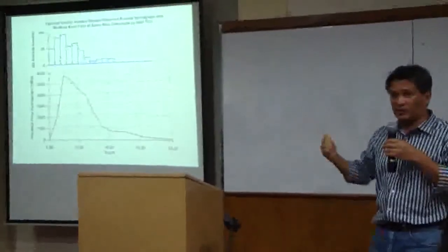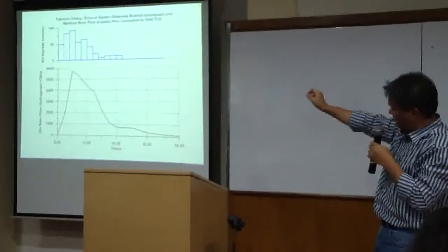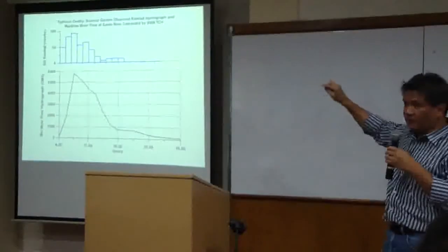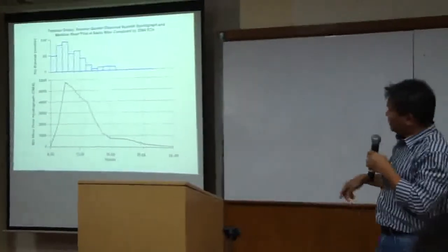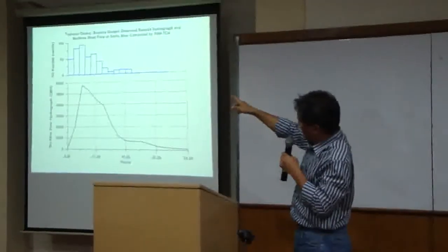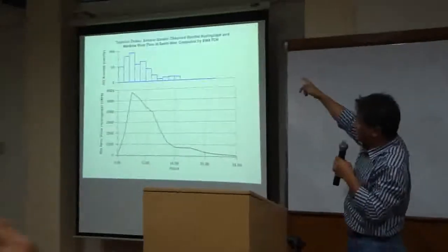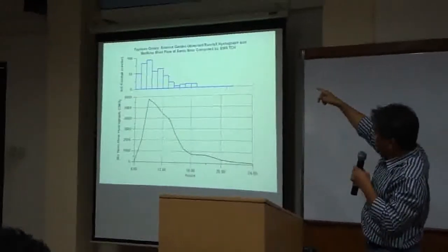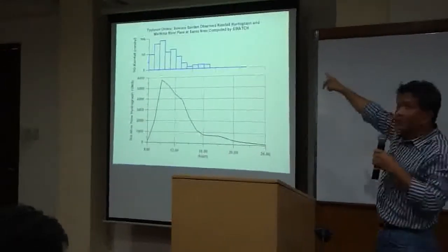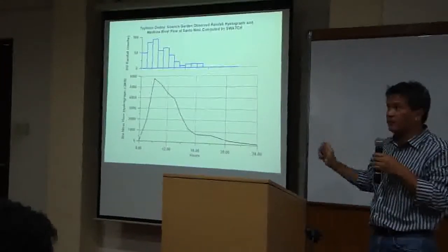Then we run the watershed model, which is a 15-minute watershed model computation. So we should assume that it's uniform over the 1 hour. So essentially, you started with something like 6 millimeters. I didn't put it there anymore, but it went to 49. It went to, I think, 69, and then 92 was the peak. That was around 11 to 12 in the morning.